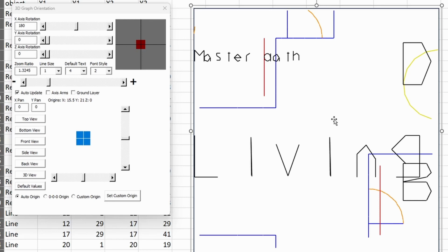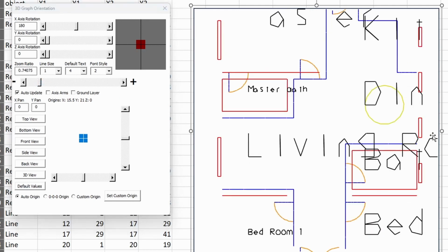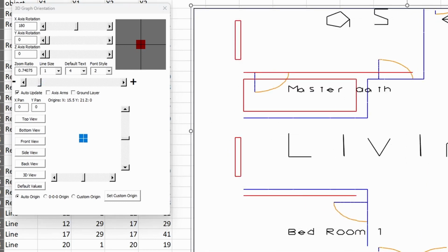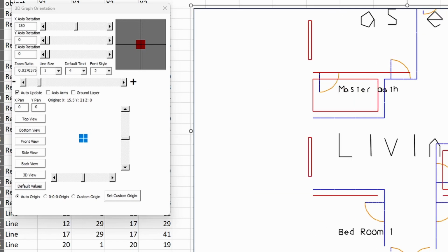so you can imagine this as being your drawing area or your graphing area. And you also may notice that whenever you zoom in closer, some of the boxes and some of the lines don't actually appear in the drawing. And that is because once ExcelDraw sees that the object is outside of the borders that it can draw, if the majority of it is outside of that border, then it's not going to draw it. You can fix this by either zooming out, or you can also stretch your graph and then regenerate your graph to allow for more area for ExcelDraw to plot in.